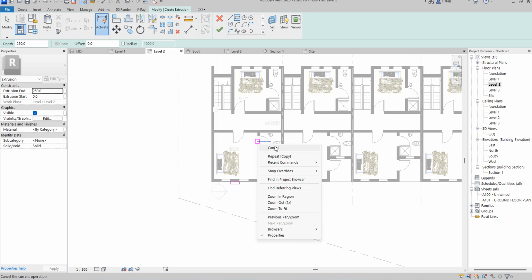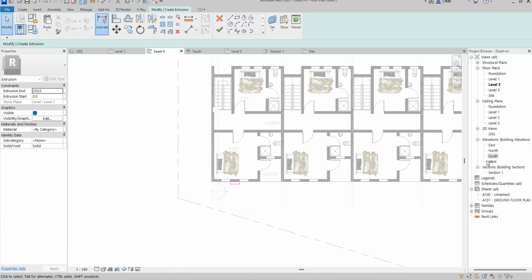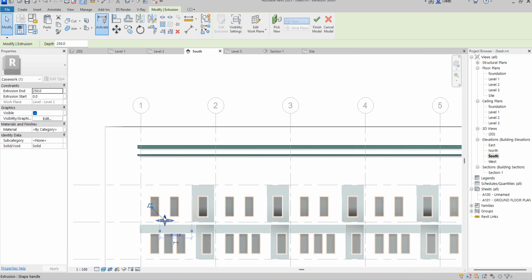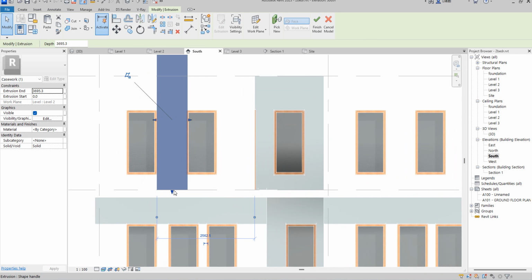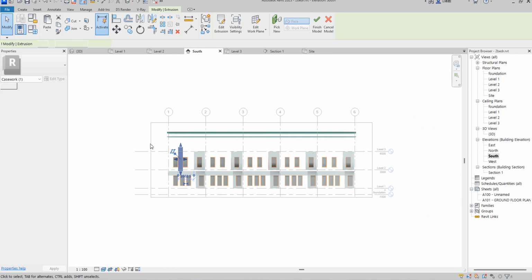So as easy as that, I'm going to go to start elevation. There it is, start elevation down. I will say finish, then I add this and shift it up. As I've shifted this one up, it has already stayed at that level, so I'm going to drag it to meet up on the ground floor, this part. So I have this in place now.